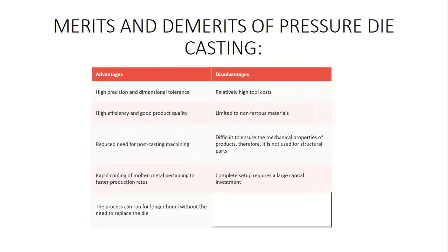So the advantages and disadvantages of pressure die casting: high precision and dimensional tolerance can be attained. Heavy tooling investment cost is required for installation of the pressure die setup.